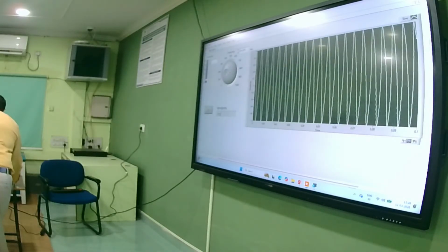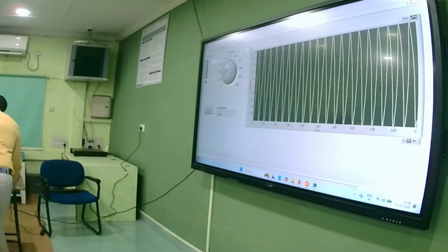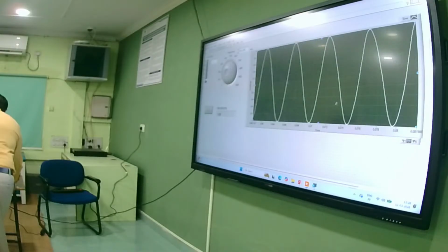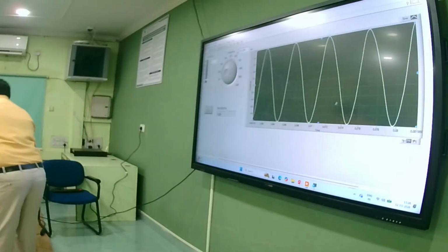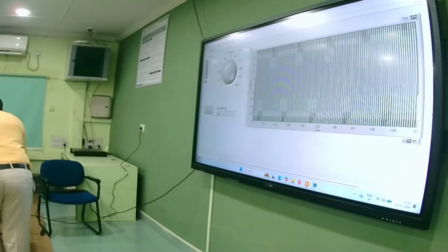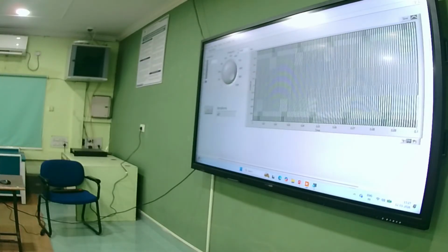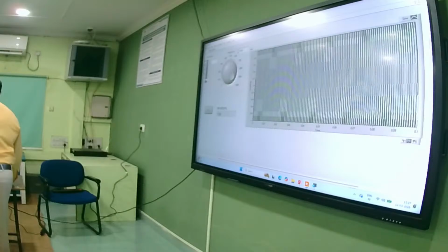So much better signal I have over there. Yes, I removed the point style. So I have proper, pure waveforms over here. Do you see the waveform curve with a higher number of samples? Now when I run here, I can go up to 1,000 also. Nothing will happen, because I have kept my sampling rate at 10,000. Here it is only 1,000, 10 times higher. So obviously I can plot the waveform properly.